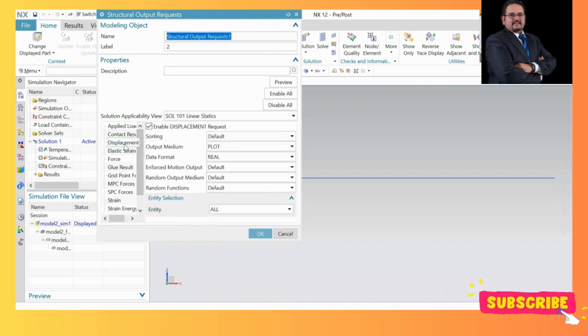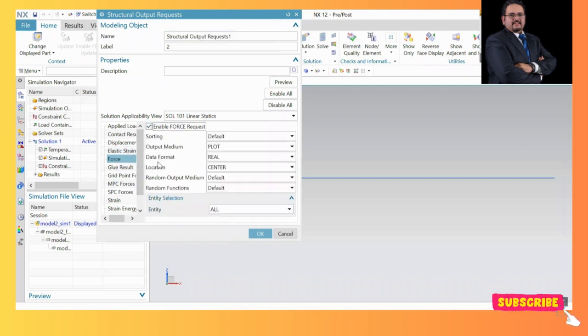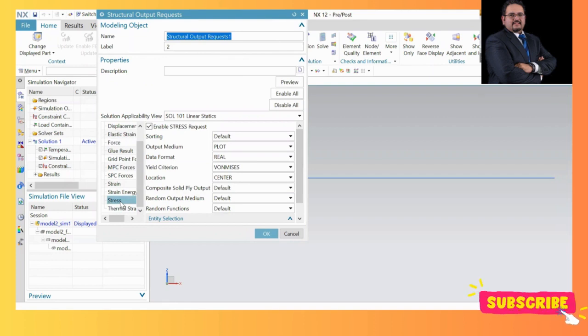So displacement is checked, so it will be included. I can look into the elastic strain. I can say I want to monitor this one as well. If I want to talk about forces, for example, I can click force as well. Whatever you check will be available to you at the end of the solution. Similarly, if I click stress, stress is already checked.